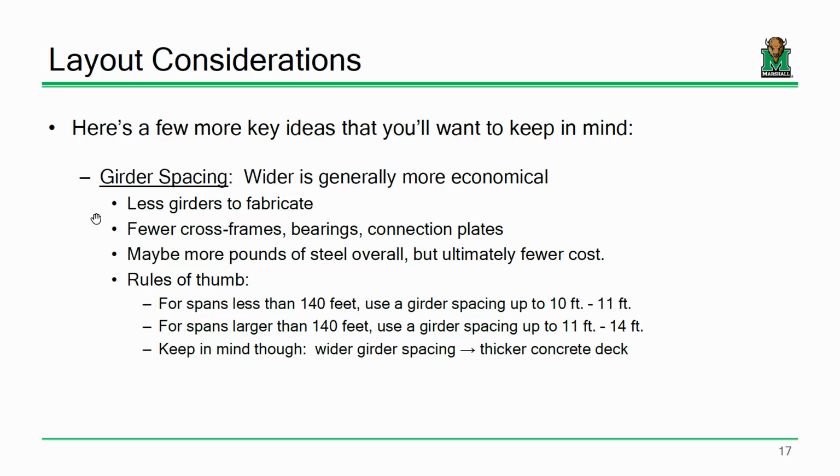Now, the wider your girder spacing, the thicker your deck is. Because think about this. You have cars driving on the bridge. Well, how does that load get transferred? Car goes to the deck, goes to the beams, goes to the abutments, goes to the ground. So the concrete deck has to hold up the girders as well. And if you have these beams that are spaced really, really far apart, you need a really thick concrete deck in order to support that.